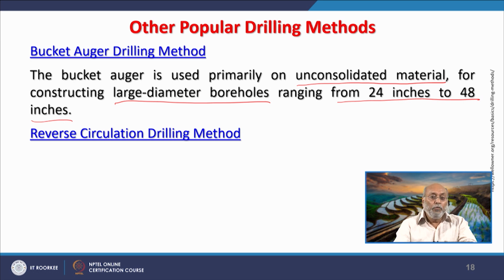In western UP or in other parts of the Indo-Gangetic plain where we have unconsolidated material, such incidents keep happening almost every year, a few times a year. That is very bad, but anyway, generally too large holes are not required. Instead of one large hole, two holes of optimum size might yield better results.